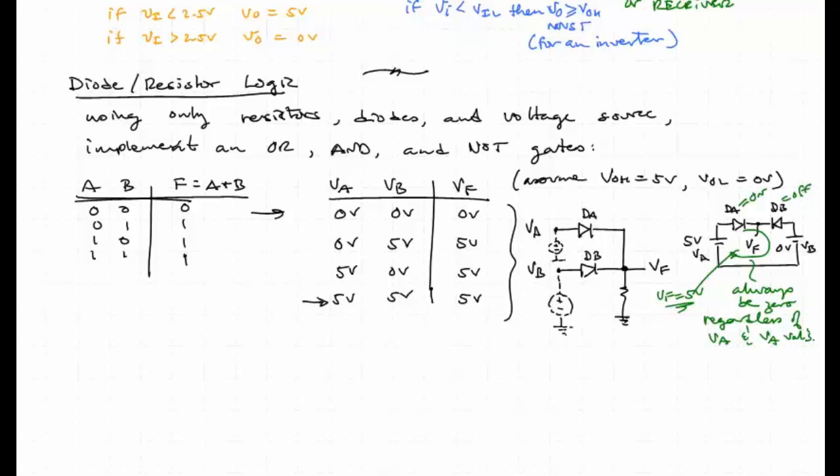Now you might say, well, why do you have this resistor in here, this R? Because I didn't show it to the right. Well, for any practical diode, you need a little bit of current to flow through it to make sure that it's on. And so this resistance is not critical, just, let's say, just less than infinity ohms. Just some small amount of conductivity. So this is a diode circuit.